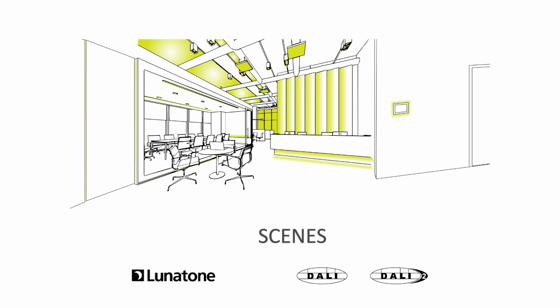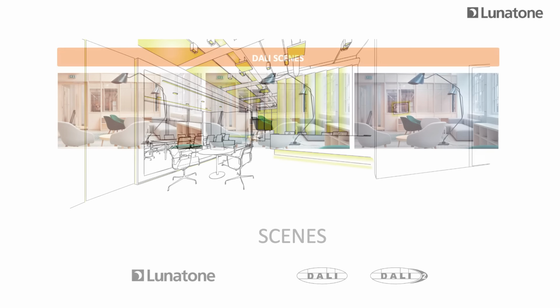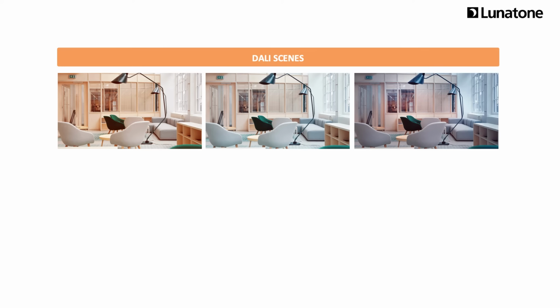A scene is used to create a specific light ambience. A well-designed scene usually includes different light values for the luminaires in the room. For example, some lights will be dimmed, some will be colored, some will be off. With a scene command, this ambience can be recalled with a single command that simultaneously sets all luminaires to these predefined values. The scene values are saved in the control gears, therefore, when a scene is recalled, the luminaire itself knows which state it has to assume.